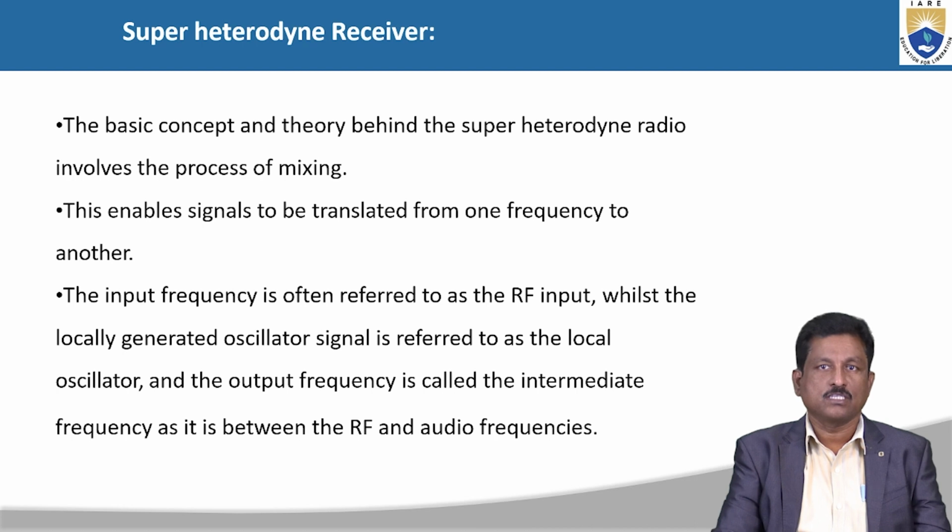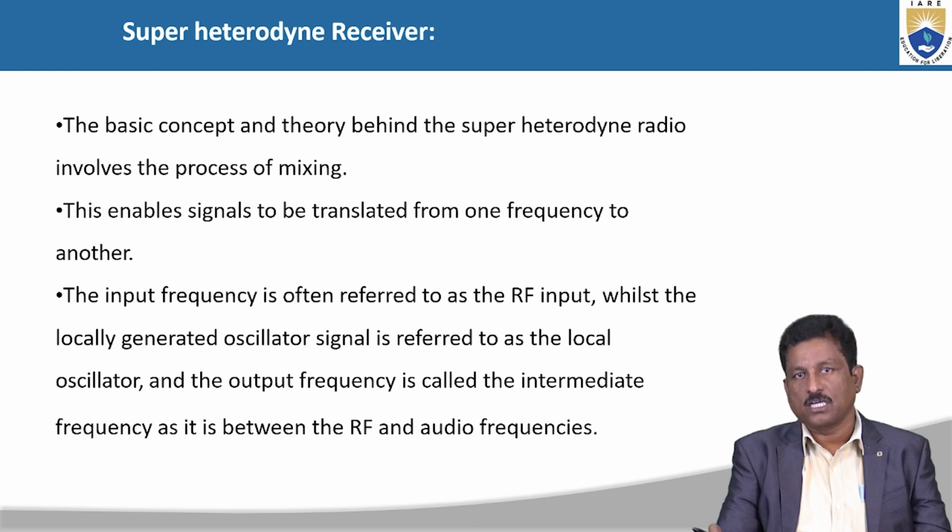Even though the received signal frequency is in megahertz or gigahertz, with the support of the local oscillator frequency, both input signals, the modulated wave received from space in the mega frequency range and the locally generated carrier signal in kilo or mega range, are mixed. By taking the addition or subtraction operation, we generate the IF value. Finally, the mixer output is always the IF value only.